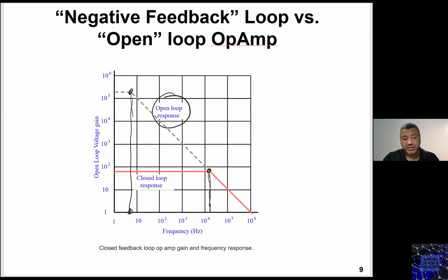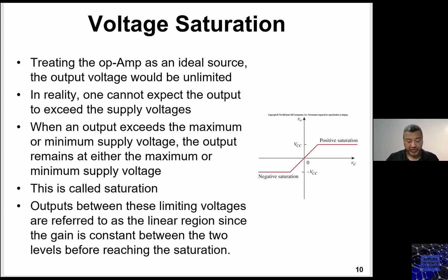Does this answer your questions? It's not damaging components, it's destroying the signal itself, distorting the signal itself, because you start having different gain levels for different frequency ranges. Okay, so this is why we tend to adjust our gain.